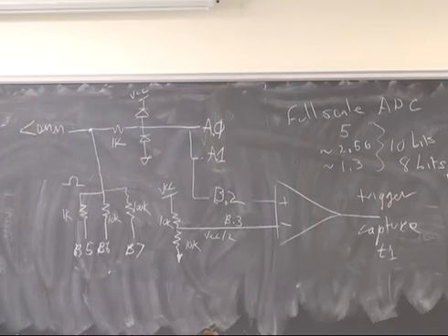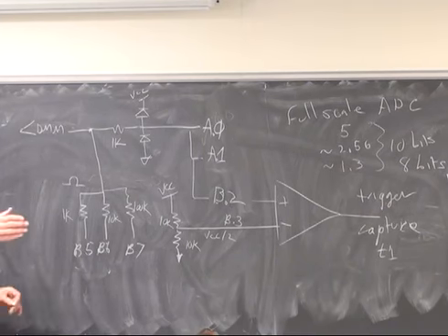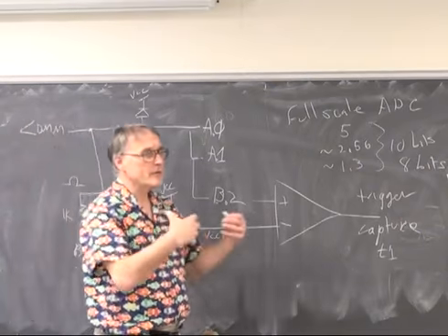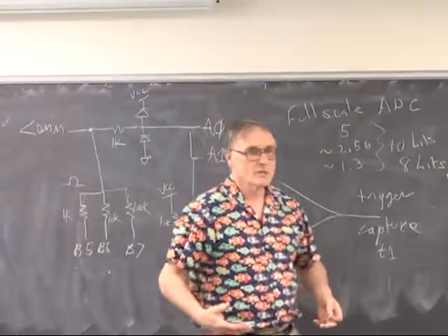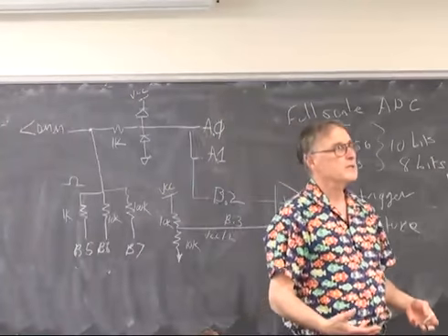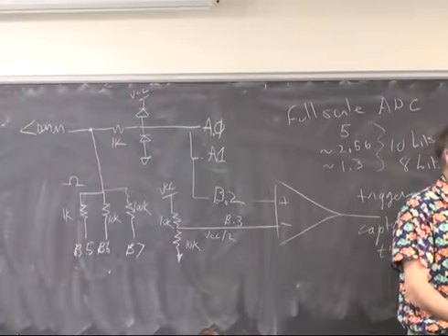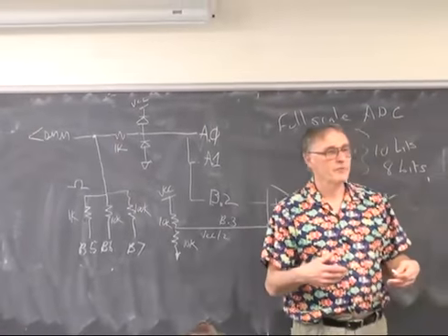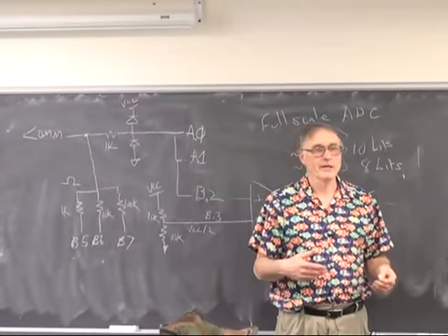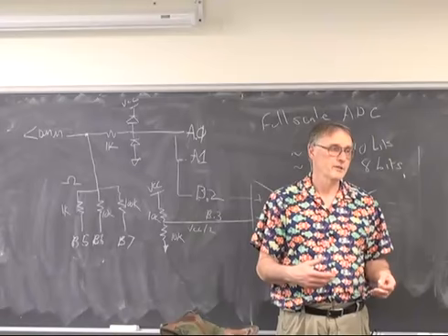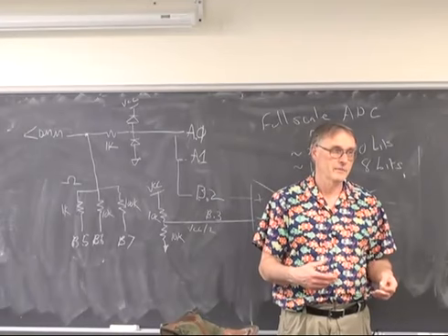What does it mean in this case to be really obsessive? It means to put the CPU into ADC sleep. You set up the conversion, you stop all of the internal processing, which cuts down the digital noise, you read the value, and then you turn back on the processing by having an ADC done interrupt.